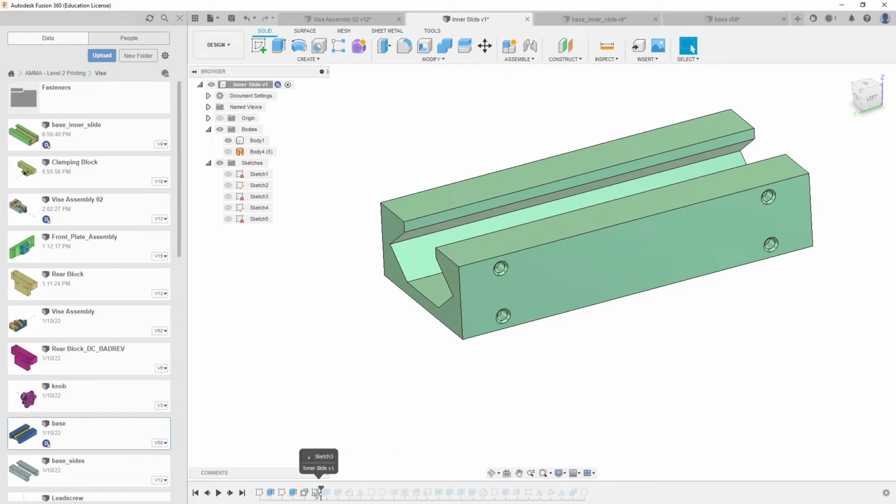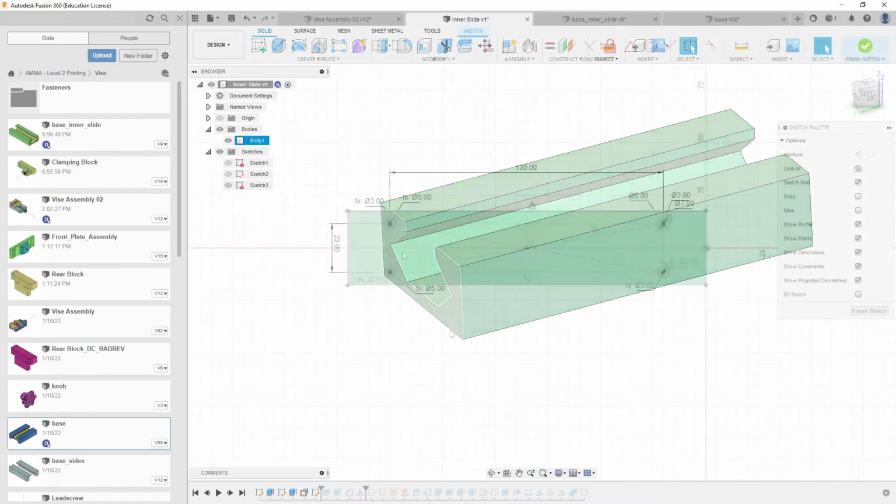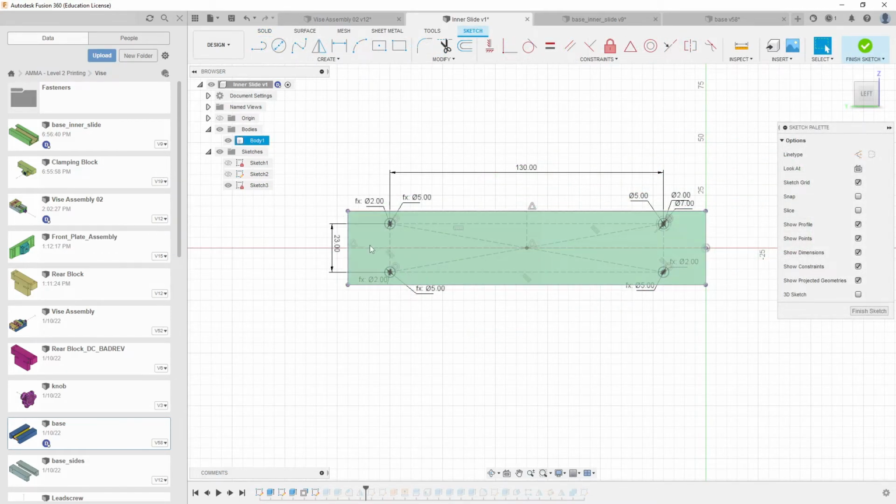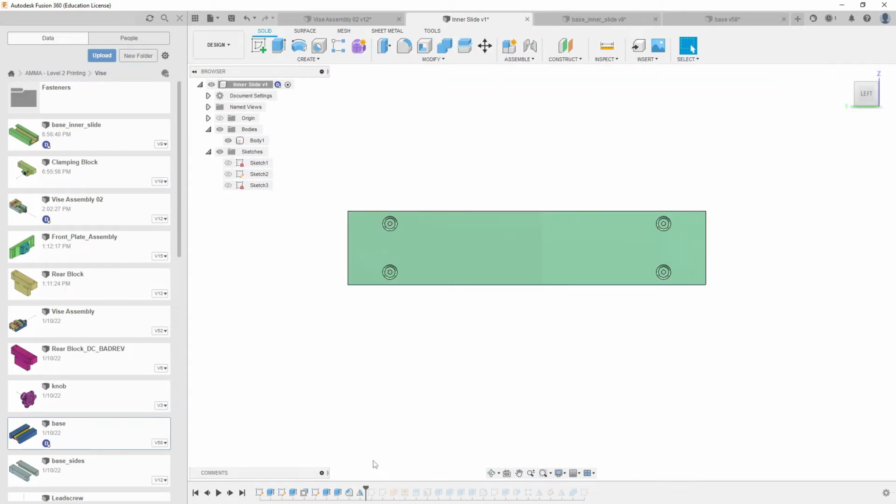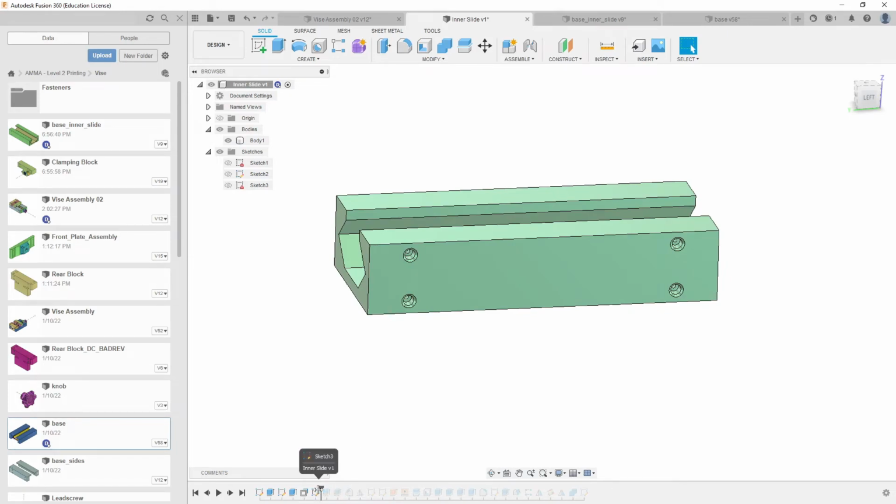So I roll it back a little bit further. The holes are gone. Okay. If I reduce this face now, if this reduces, then this center point that we have right here possibly might move, right? Because it was based on this midpoint line. So that would be a problem. So I do not want to roll back prior to the hole creation.